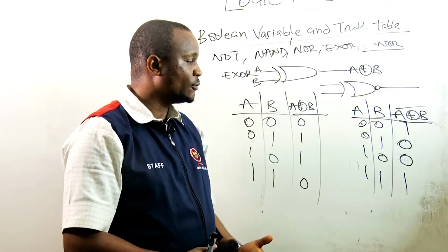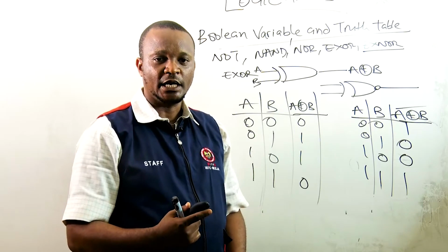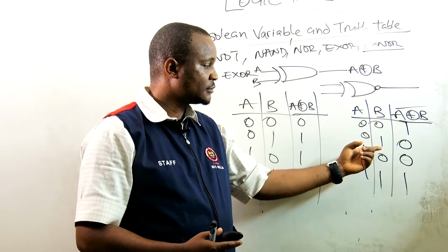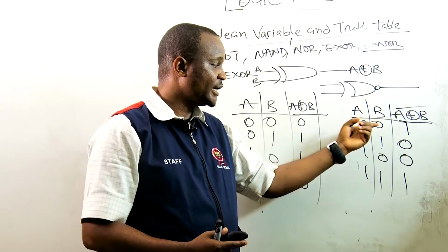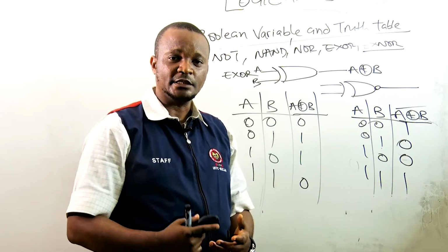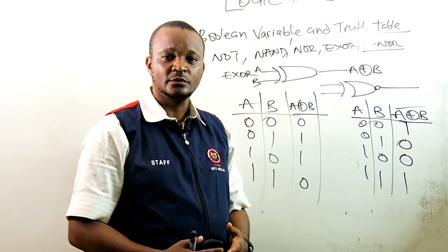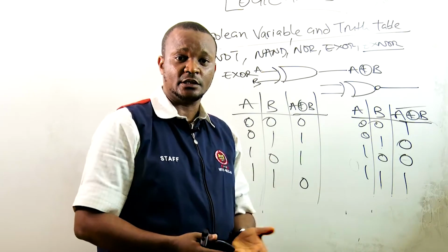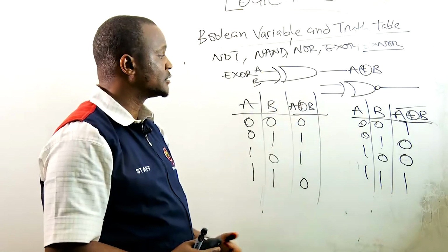So probably you're trying to compare the levels of a fluid, probably water in the tank, and you don't want them to be the same. Okay, so whenever they are not the same, you have a 0. Wherever they are equal, you have a 1. And this logic 1 can mean a high, that is, turn on something. So it could be turning on an alarm, it could be activating something else. So that is how these comparators, or rather these logic gates, work.